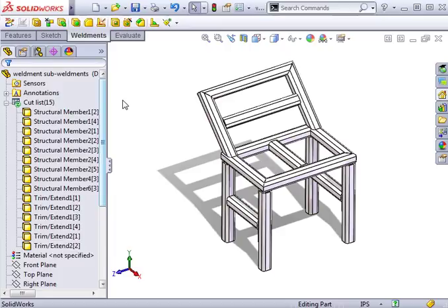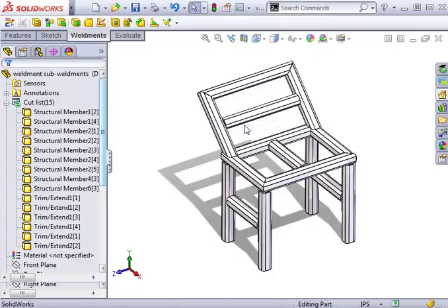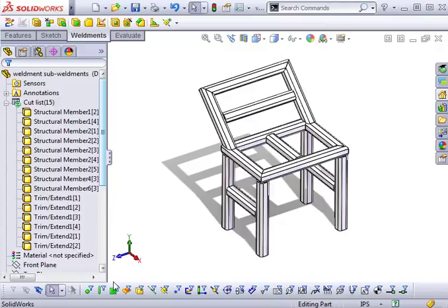Since items are difficult to tell apart from the list itself, I recommend enabling the solid body selection filter. You can do this by first activating the filter toolbar by right-clicking in an existing toolbar and enabling Selection Filter, then selecting Filter Solid Bodies. I want to point out that when using selection filters, I tend to use the F5 key on my keyboard. This is a SolidWorks shortcut, allowing you to turn the filter toolbar on and off with a simple push of a button.